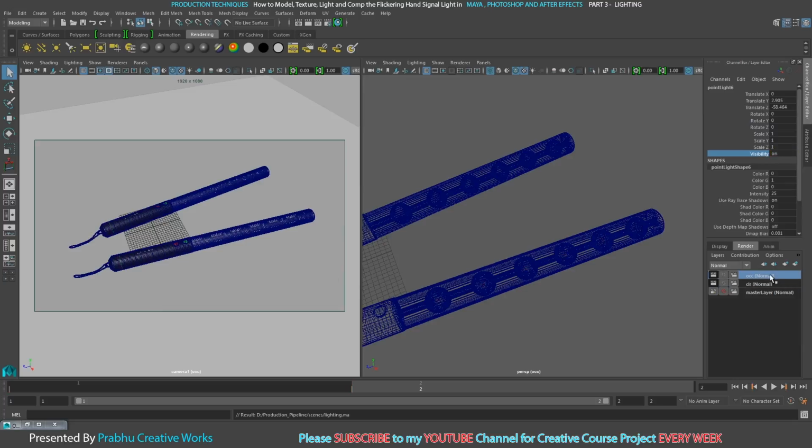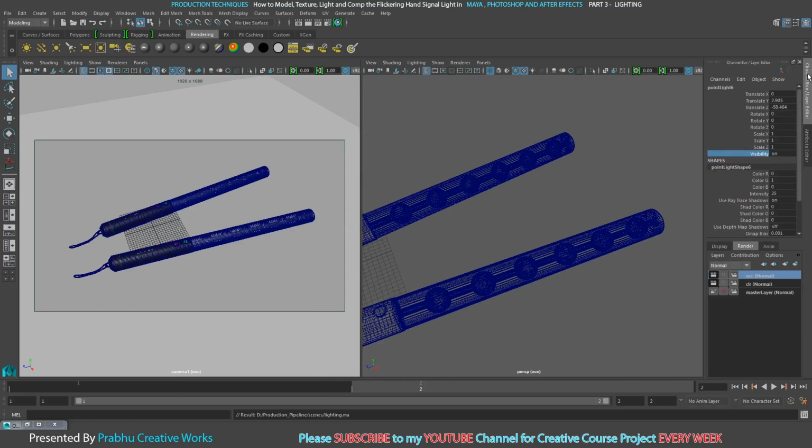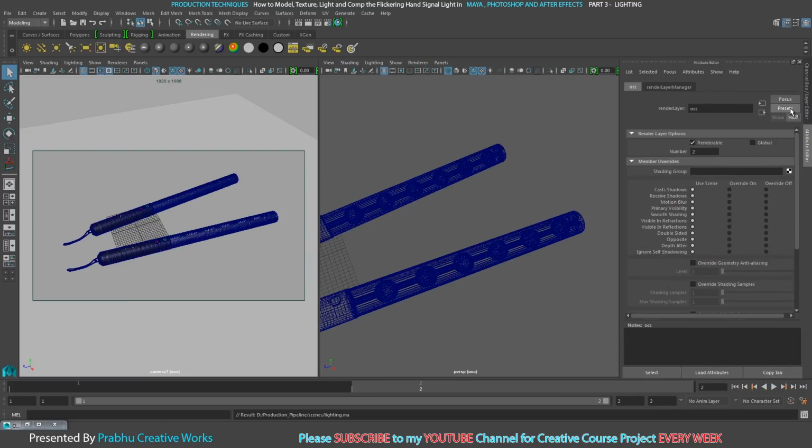Before that I want to set my occlusion pass. So right click and choose attributes. So go to presets. Sometimes it will not enable, so do it again. Go to the channel box and layer editor, right click and choose attributes, and choose preset, and choose occlusion.